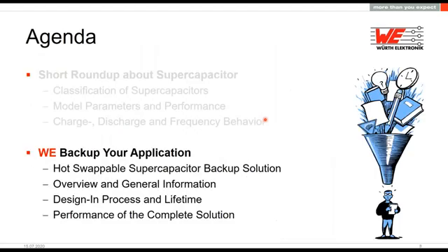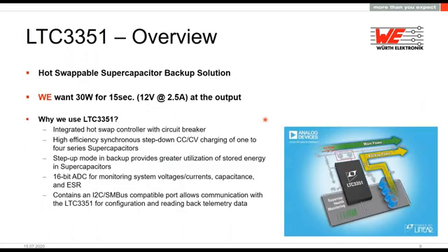This was the short roundup about the supercapacitor technology itself, and now we will dive into the application we built, the solution we built. As you see, we use an Analog Devices IC for the voltage regulation in our demonstration. The advantage is that the IC has some very nice features like hot swappable and high power capabilities. We defined our application for 30 watts for 15 seconds. So at the output in a backup case, we have 12 volt and 2.5 amp.